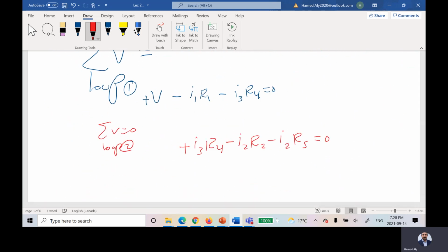Any question for Kirchhoff's voltage law and Kirchhoff's current law? Yes. Could you please raise your voice? The direction of the current doesn't have to be the same as the loop direction. It doesn't matter. He is asking about the direction of the loop for the rotation and the direction of the current. It doesn't matter. You will rotate in a specific direction and you have the signs for each branch.